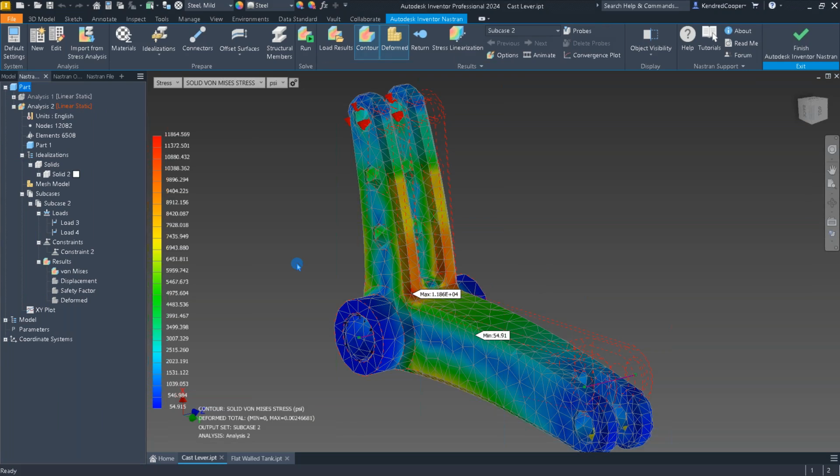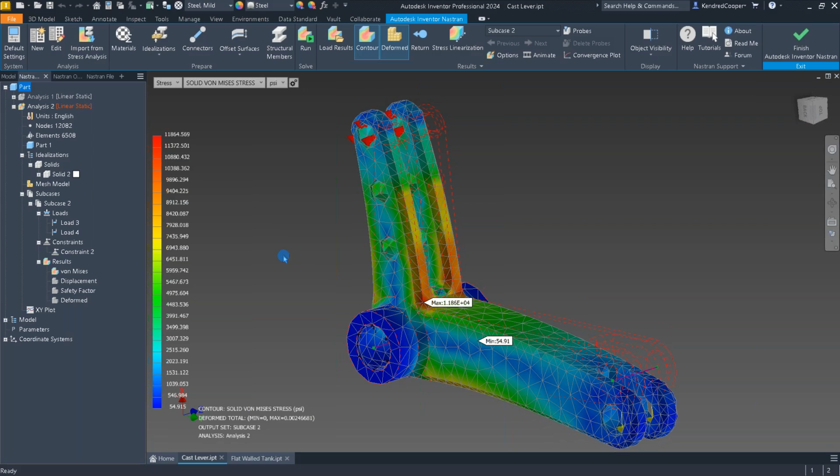Now, with this particular weather map that shows up, a lot of people want to step into this and say, okay, it's red down there at the bottom of the forks. That means it's going to break. Yeah, no. Red does not always equal bad or break location, or failure location is what I should say. Red simply indicates the worst case depending on the test you're looking at. And the weather map will change color transitions. You go to a different type of analysis, the colors will actually invert.